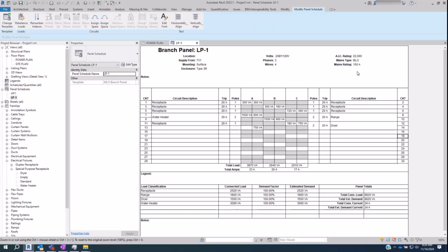I'm trying to make sure I understand your question, because I heard two different concepts in there from my electrical standpoint. I'm going to answer the two concepts, and if I didn't answer your question, let me know. When I said 80% rated panel, that means the breaker protecting this panel is good for 100% of the nameplate of the breaker for 3 hours. Anything after 3 hours, it's probably going to trip because it's an 80% rated breaker. That's the idea. They're much cheaper.